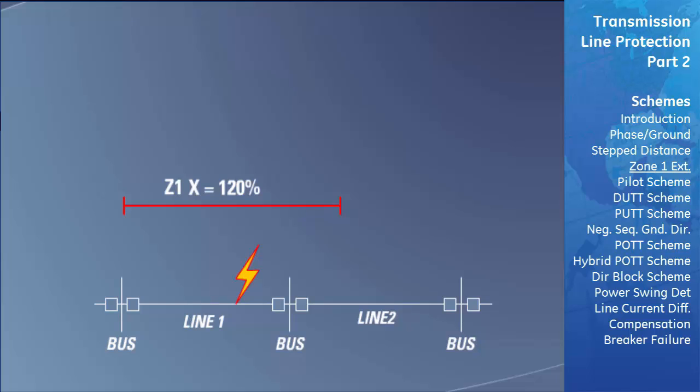Once the breaker is opened and the fault is cleared, the relay will then automatically reclose the breaker and re-energize the transmission line. Once the line has been reclosed, the relay will then use the standard Zone 1 characteristic and now underreach to only protect an area within its own transmission line. If the fault that occurred was a permanent fault and the fault is located within the transmission line's newly shortened Zone 1, the relay will trip and again open the circuit breaker to clear the fault.